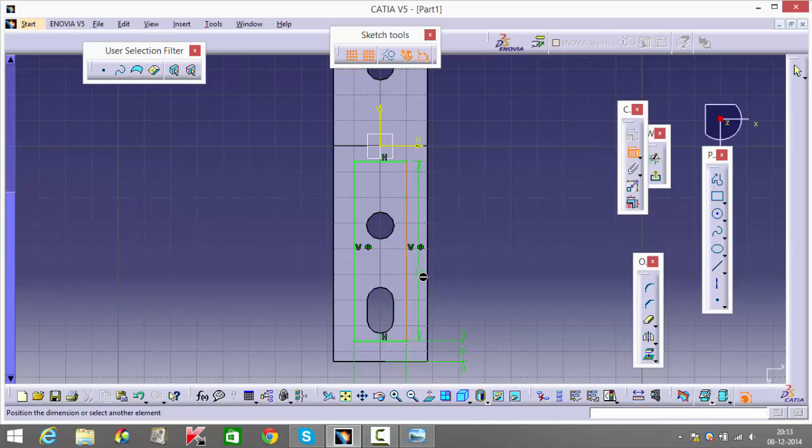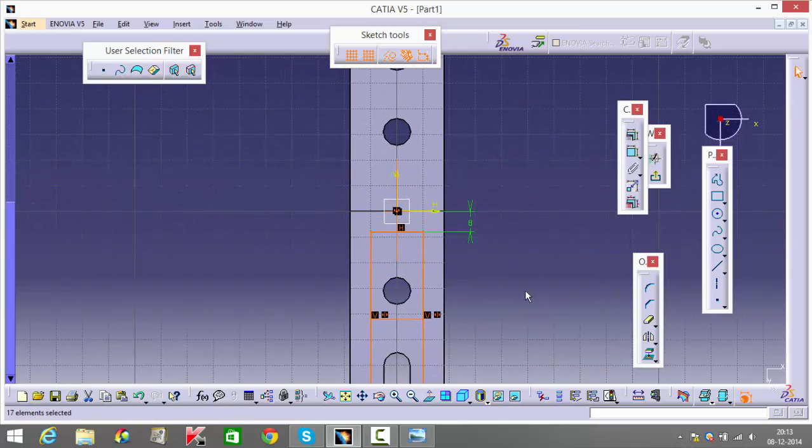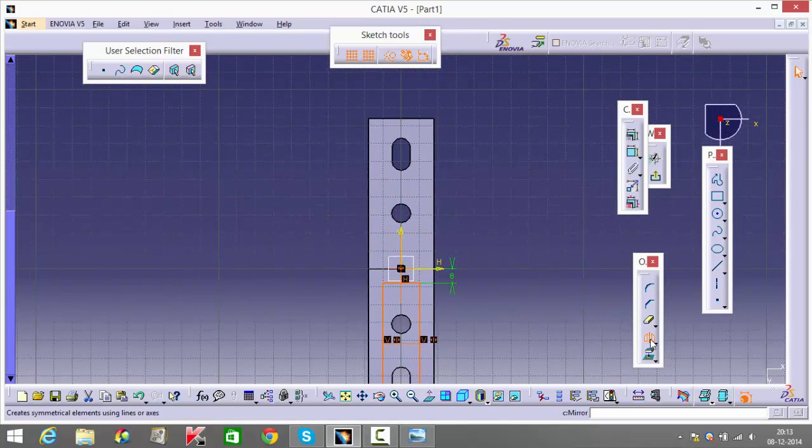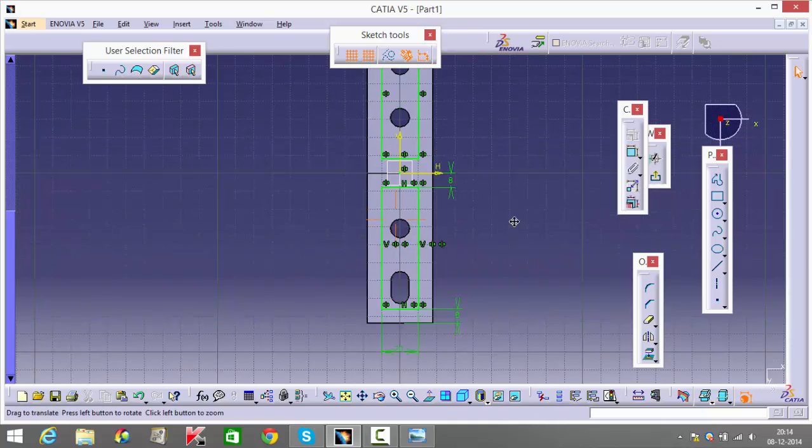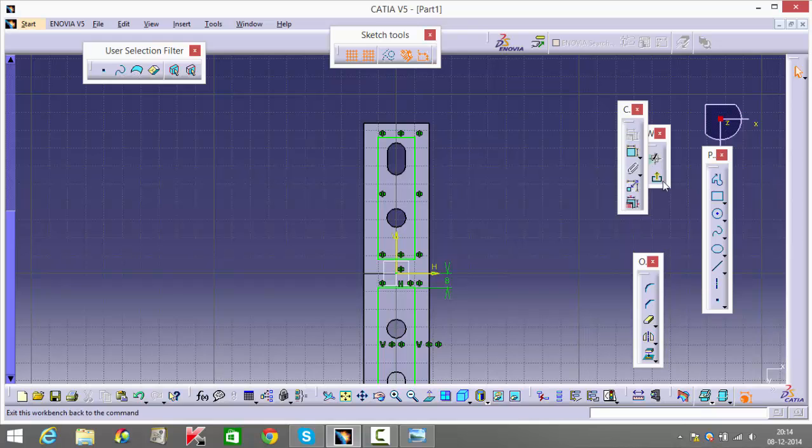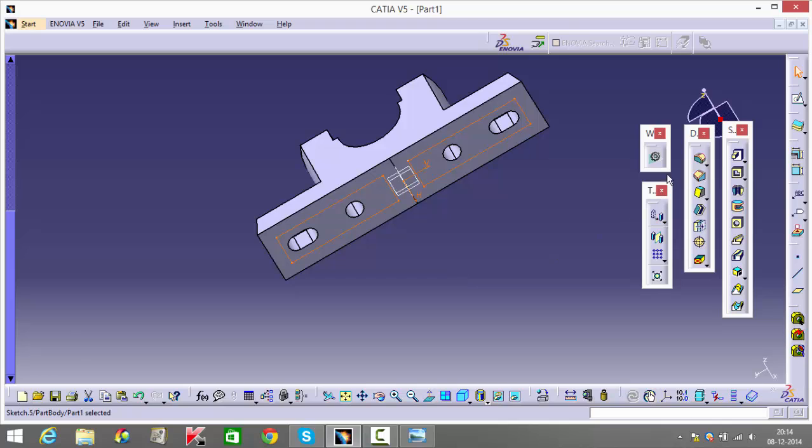So are these distances. Okay, so it's automatically constrained since I mentioned that as 20, and this distance is given as 8. Once I have this, again I'm going to select this whole portion. See, this is the best part about Catia. You have several options and you need to venture out and see how these options work. You don't need to individually make all these different parts. You don't need to make one box here, make the constraints, another rectangle here, make the constraints. All you can do is just make one and mirror it if you require it. In some cases you'll really need to do it individually.